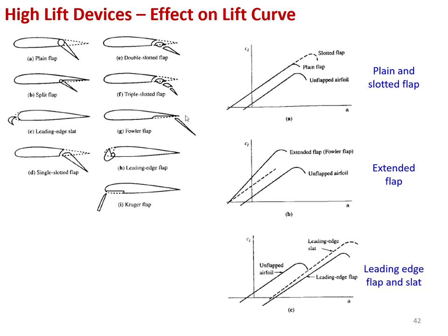So we can have different examples of slotted flaps, triple slotted flaps, double slotted flaps, and so on and so forth. If you use an extended flap or a Fowler flap like this, not only are you going to increase the maximum lift coefficient, but you are also going to increase the lift slope.